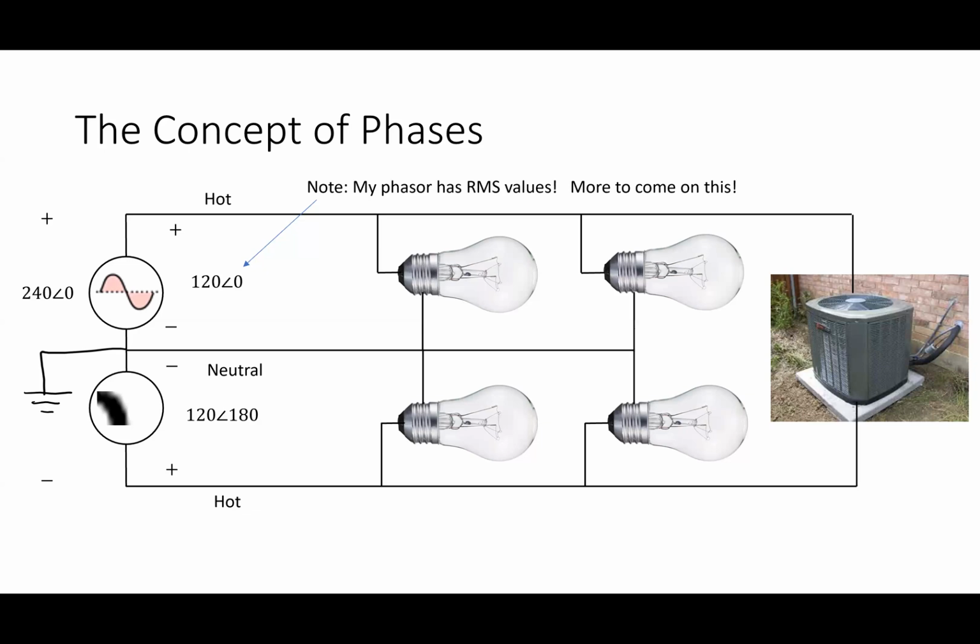What's the peak value, or in other words, what's the amplitude of that sine wave? It's not 120, is it? Around 170. So how'd you get that? 120 times what? Square root of 2. All right. The peak value is 120 times the square root of 2.